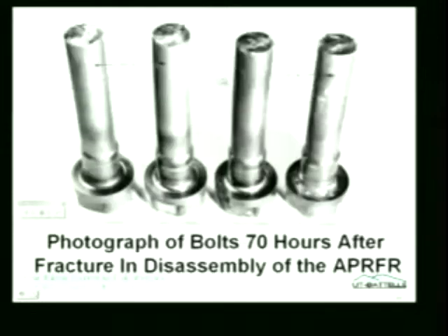For you engineering types, this was my first experience with stress corrosion cracking. Okay, we took these bolts, and they looked fine, except they were broken here, and we put them on a table. And then we watched them, and guess what? Spiral cracks begin to appear, like on a barber pole, and eventually they just fell apart.